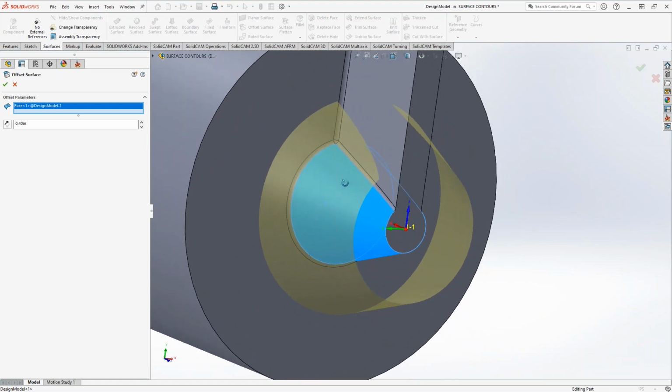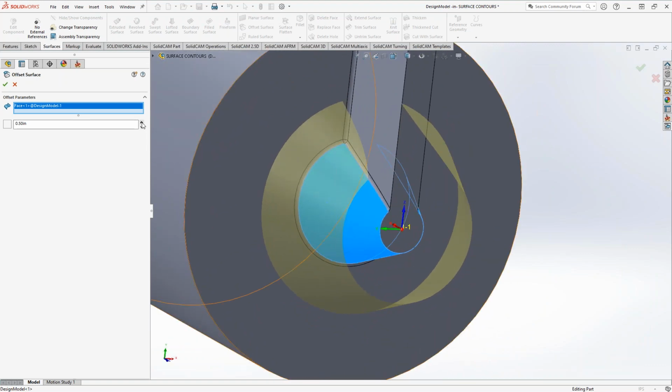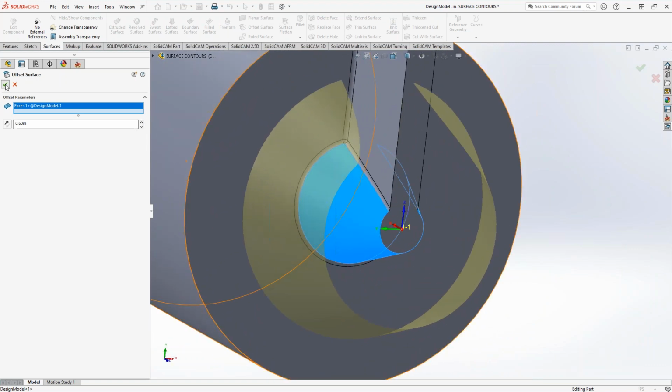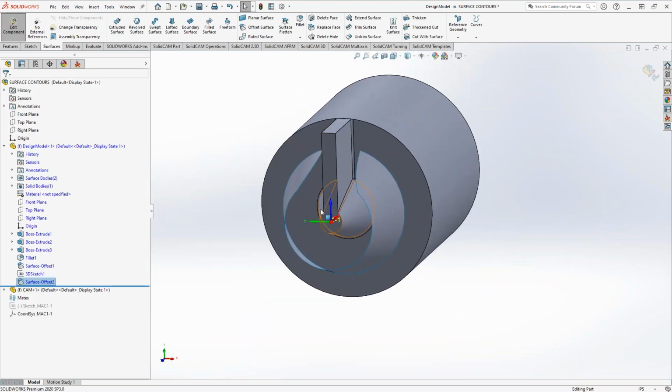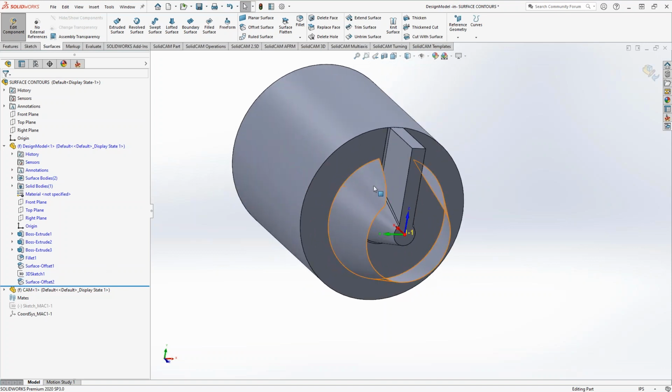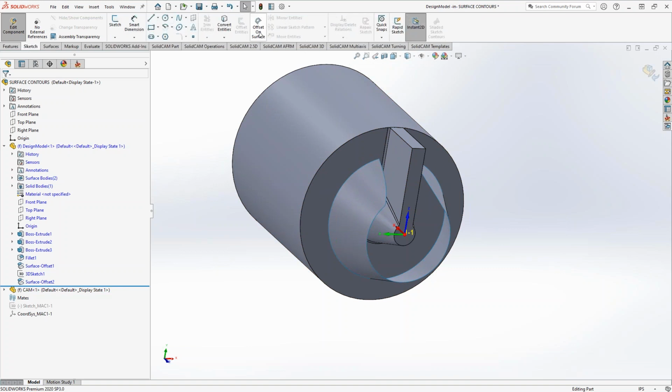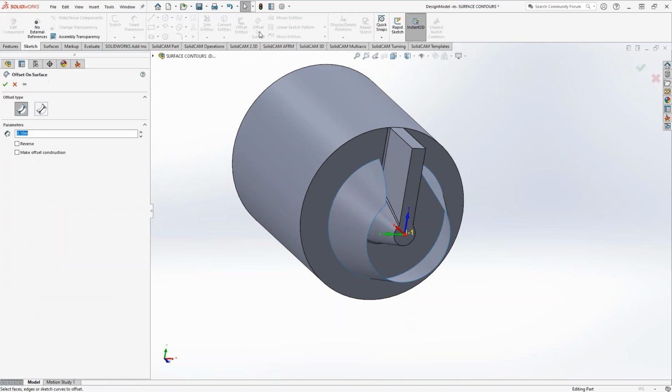Hopefully that's coming through. So let's say we make that guy there. I'm going to make it a little bigger than my other one so we can actually really see it. Now that makes an offset from that surface. All points on the original surface and this surface are, in this case, 1/2 inch apart. But how do I get that nice 3-dimensional kind of curve that I wanted to use for my tilted curve? That is under Sketch and then Offset on Surface.